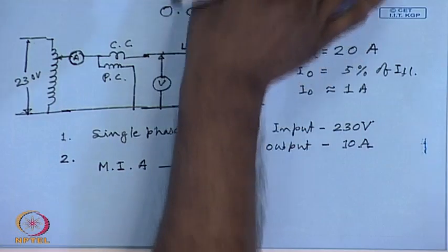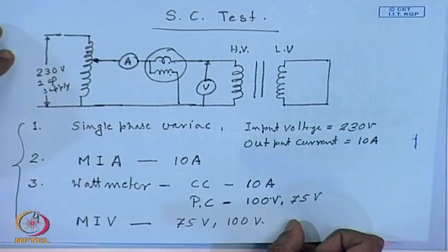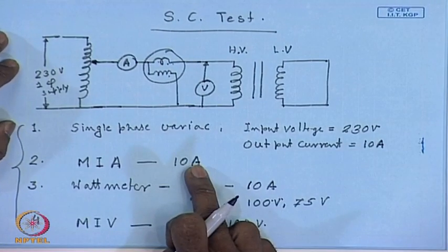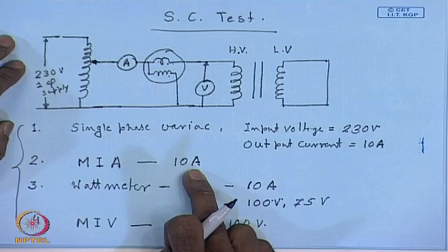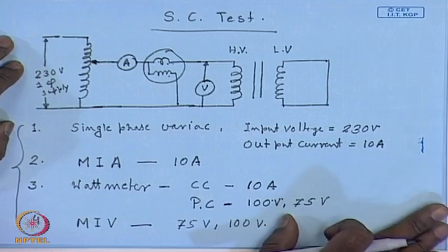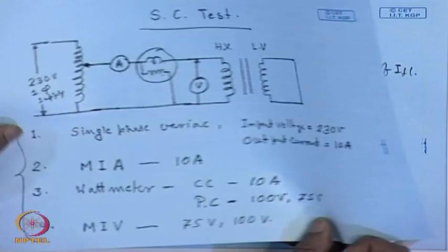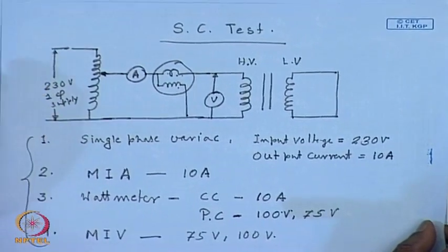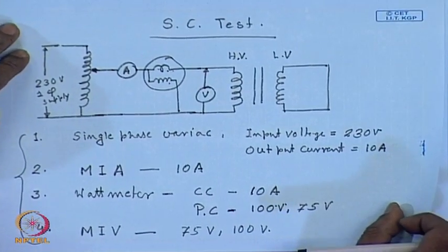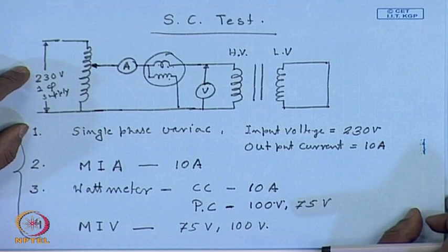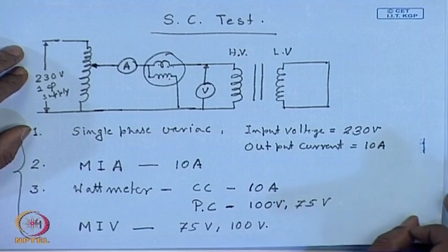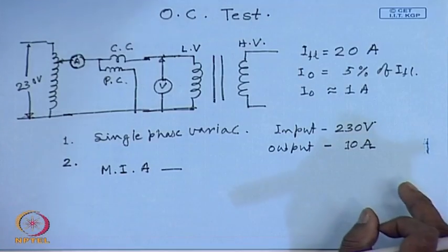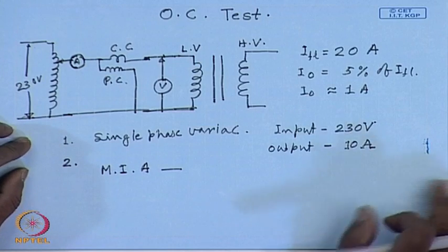So, again, whichever ammeter we have chosen for the short circuit test could have been sufficient. However, this current rating of 10 ampere is too large for performing the open circuit test. The problem is, the higher the maximum range of the meter, the lower its accuracy becomes, particularly with moving iron equipment. At the lower end, the accuracy suffers. Therefore, it will be necessary to choose a lower rated ammeter.